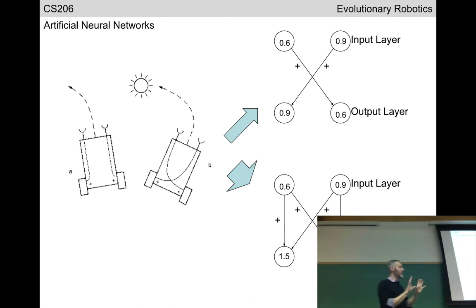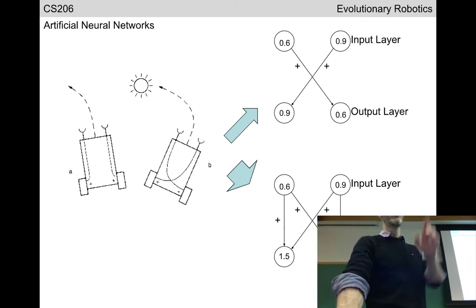We'd like to have that range beforehand so that we can then scale that range to the allowable range for the motor, right? So you could get something like a value of 200 here if we're not careful about the synaptic weights, and we might tell the wheel to spin at 200 revolutions per second, and you'll burn out your motor within a tenth of a second. Okay. That's one reason why we do it in robotics.